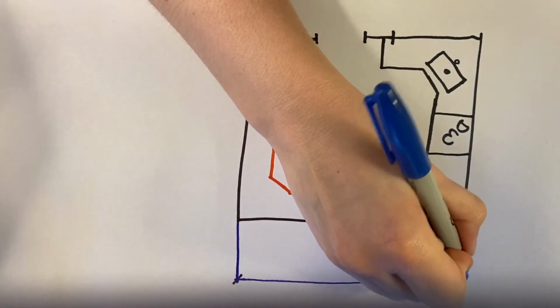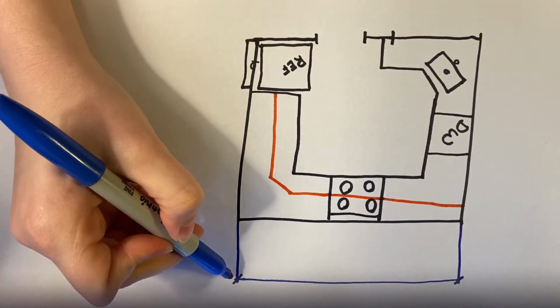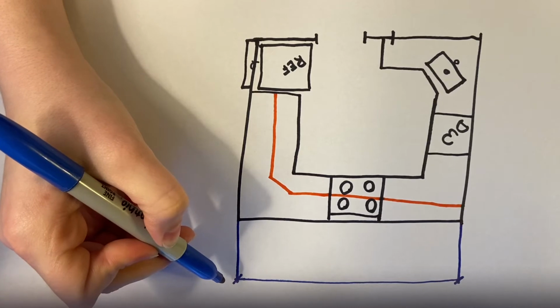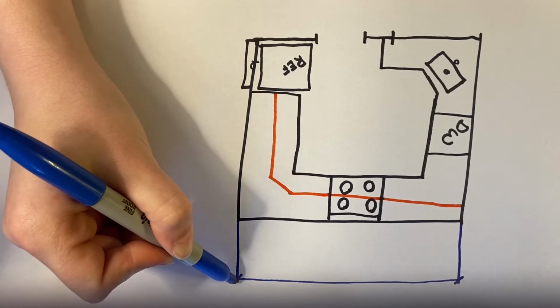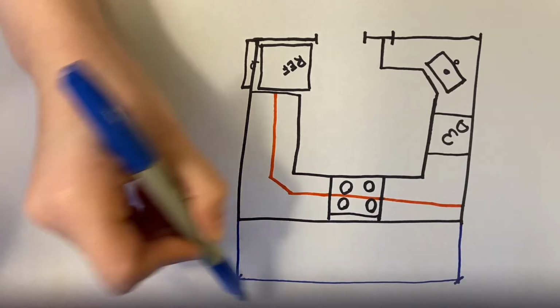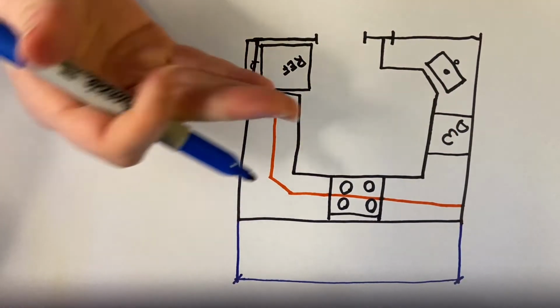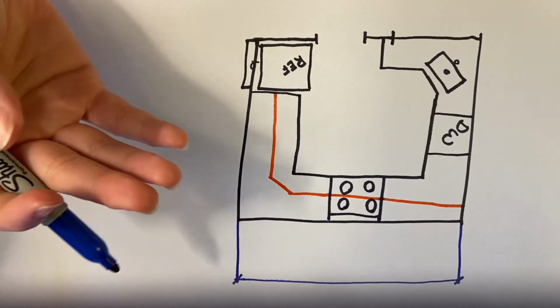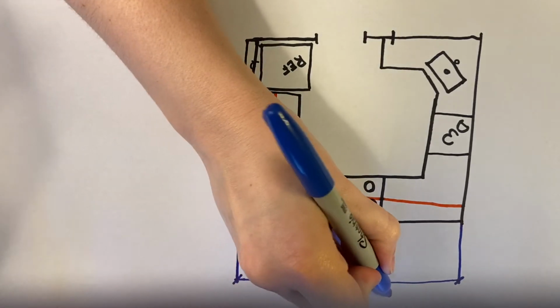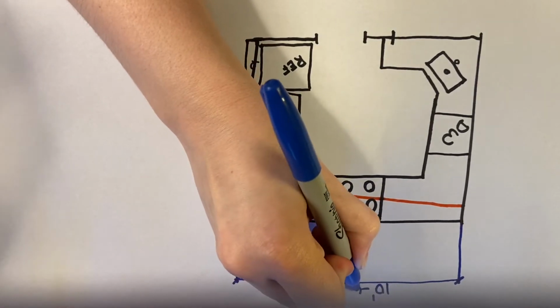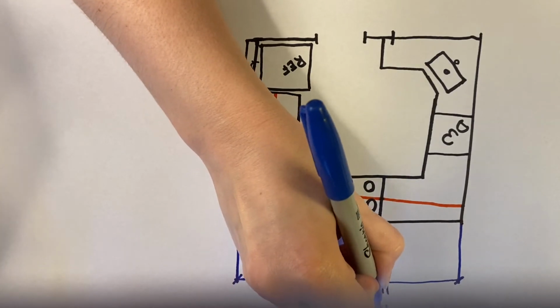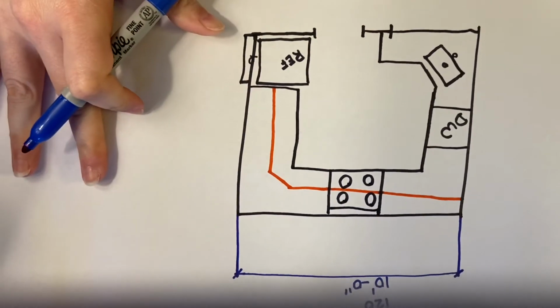and then just draw a straight line across with little tick marks. These little angled tick marks are going to notate where the measurement ends. So every time you see a tick mark, a new measurement will start. So in this case with the overall, you're just going to have the first and the second one. And so for the sake of this, we're going to be using arbitrary numbers. So we're going to use 10 feet for this, or 120 inches.